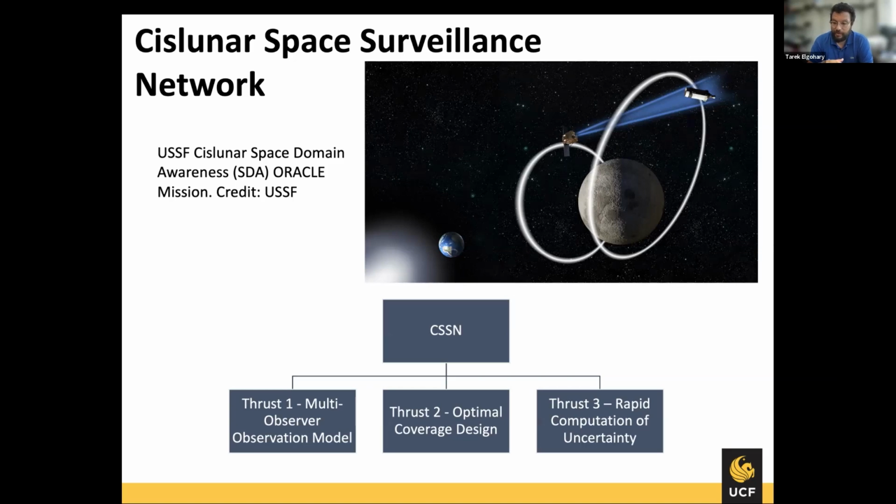The dynamics of that space are very challenging. Obviously, from basic orbital mechanics, we know that things around Earth orbit in ellipses or circles. Things are more or less well behaved. Most of the uncertainty, if you're close enough to the Earth's atmosphere in low Earth orbit, comes from drag or some external perturbations that were not modeled, but we're pretty good at modeling the Earth environment in general. Beyond Earth, this gets you into what is known as the circular restricted three-body problem, or the three-body problem in general. And dynamically, that could be a chaotic system.